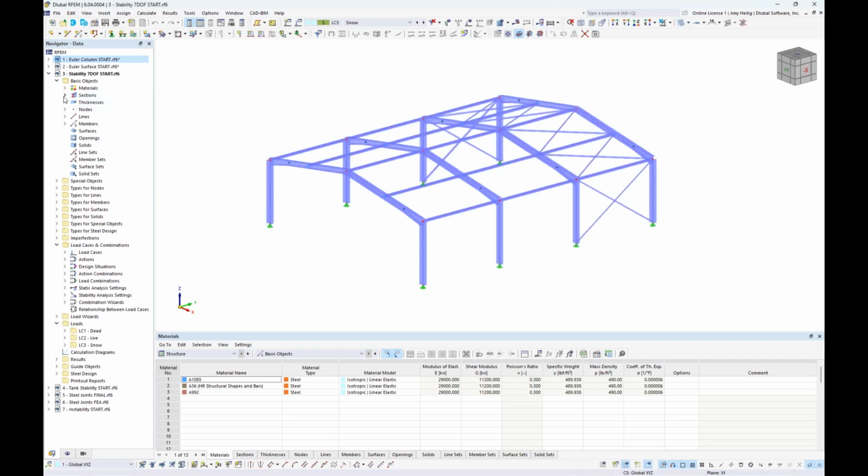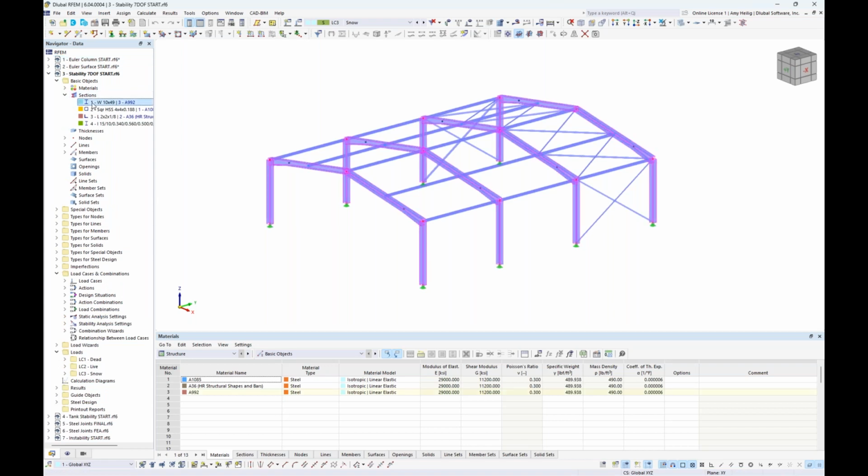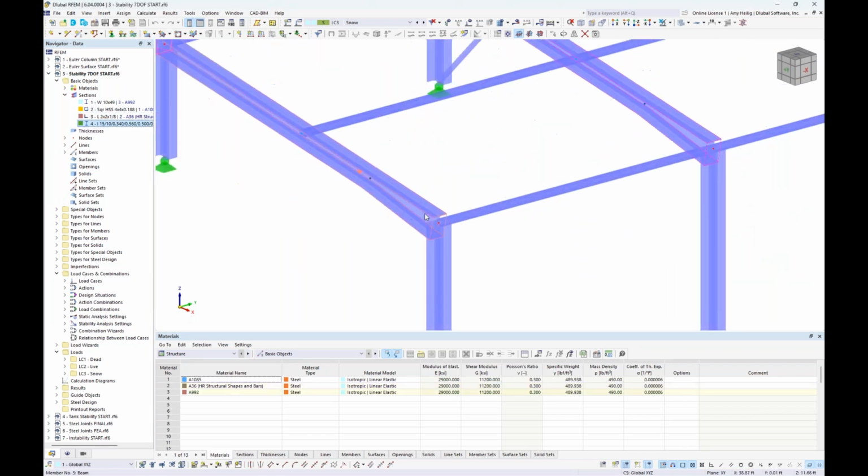If we want to do a quick overview, the cross sections are from the AISC database. So we have W10x49s. We have some square HSS sections spanning between these moment frames, single angles for our cross braces here, lateral bracing. And we also have a very small taper for this beam member. In particular, this is at 25% of the member length before it frames into the vertical columns.